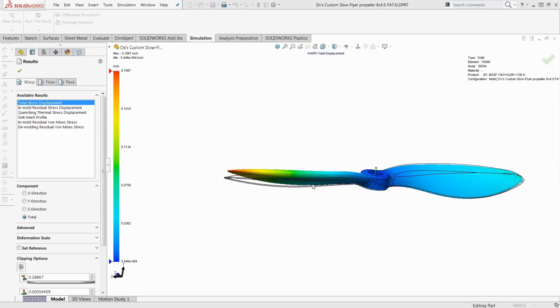Okay, so Arvind, you're saying that you can save the deformed shape that the software gives us, and we can save that as a 3D model and print that and then test it? Absolutely. So you can run tests to look at the form, fit, and function with an STL 3D printed model before you create your first mold.